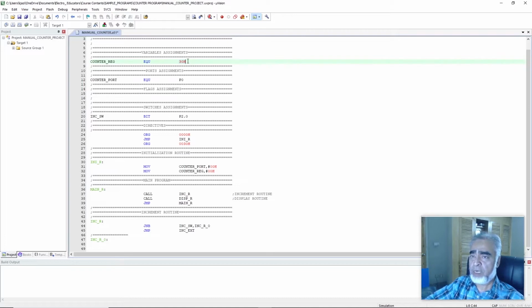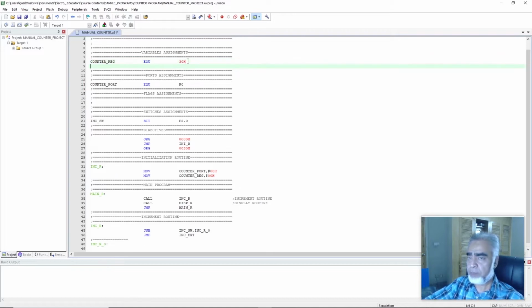And here we will add another variable, that is dbreg EQU 31H, that is the second address of general purpose RAM, and we will initialize this variable in our initialization routine. So here in the initialization routine, we will write,